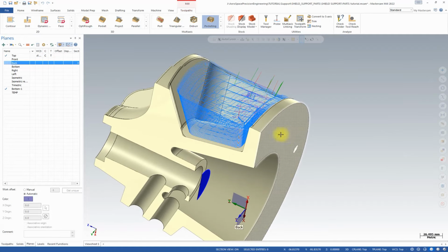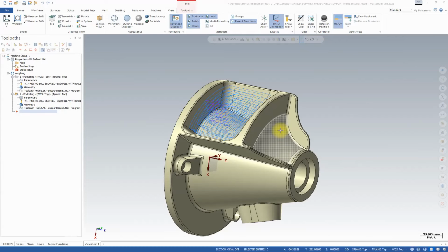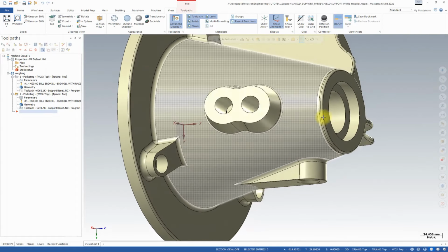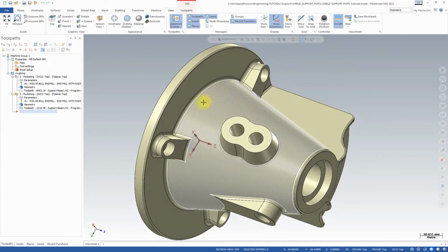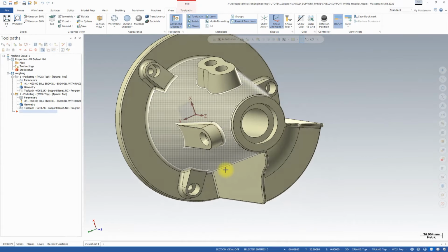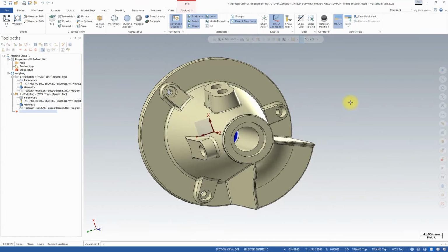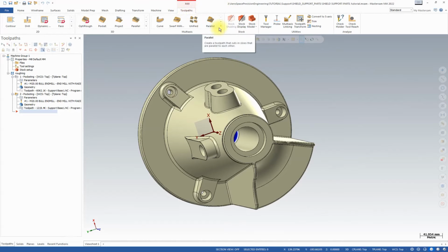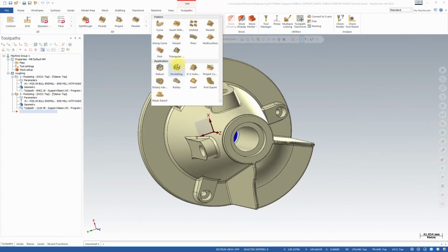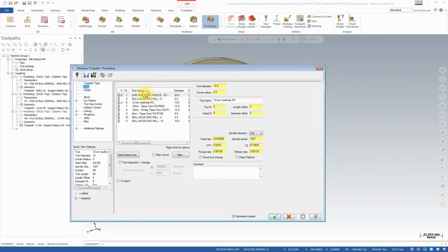Okay, so with our next tool path, I'm going to show you how to set your pre-finishing operation. And we are going to pre-finish this floor here. And again, the purpose of this tutorial is to show you what you can do with your multi-axis pocketing toolpath. It's just to present to you how you can target certain areas and what you can do to tell Mastercam what features you want to machine and to target only features you want on your 3D model to be machined.